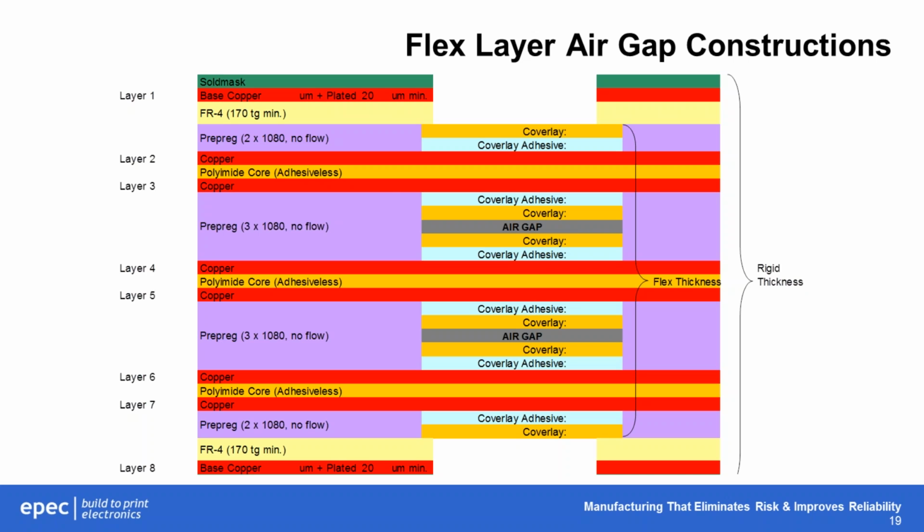If this design was attempted to be done with all 6 layers bonded together, it would not meet IPC 2223C. There would probably be some very significant via reliability issues, and the flexibility of the flex section would be very much limited, almost to the point of not being functional.